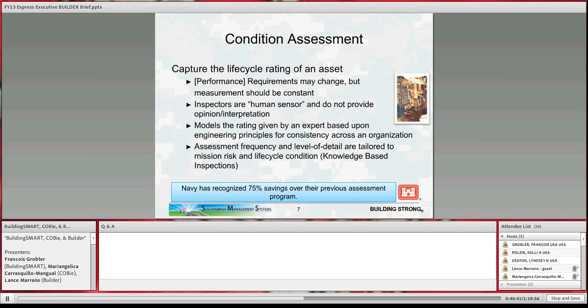Likewise, at the end of the life, I really don't need to collect a lot of data about the tears and the seams and the blisters and the flashing separations. The roof's bad. I know it. It's shot. It's just time to schedule the whole thing for replacement. In the middle is where we can right-size some more data collection to get more diagnostic information to help properly refine what the repair methods might be.